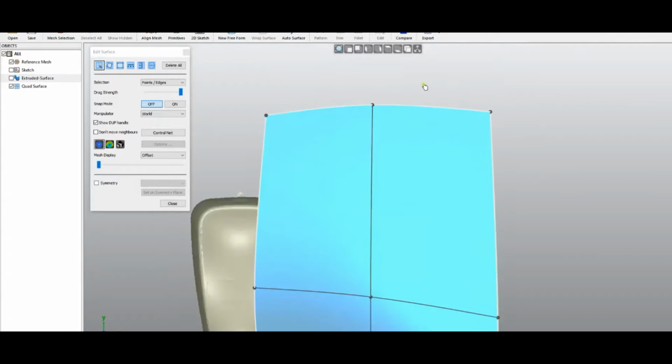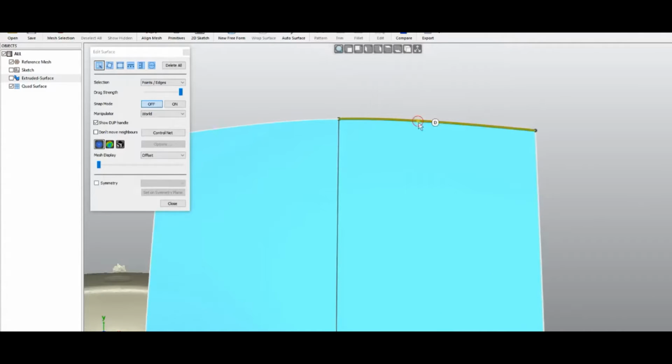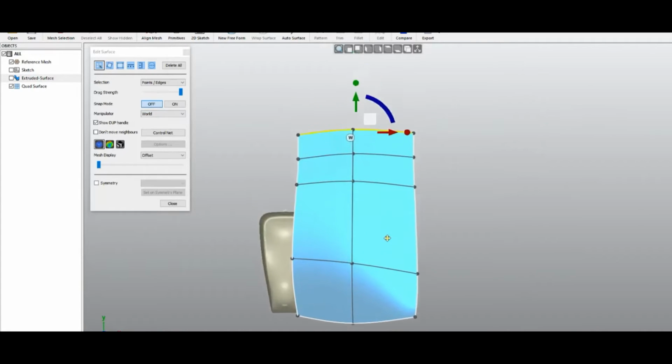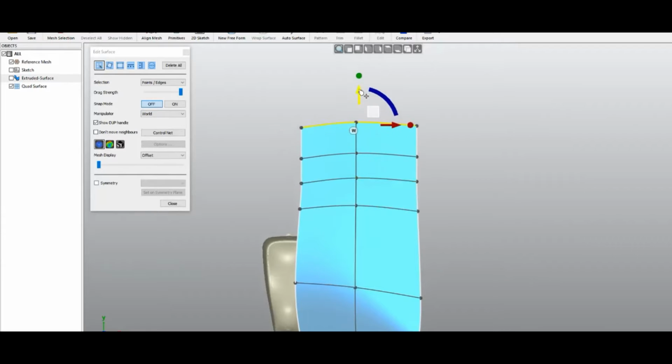Another way of duplicating an edge is, if you double click and select everything, you hold the Alt key, and instead of using the D sign, if you hold the Alt key while holding it and then you move, it will duplicate the edge. This is useful if you want to make really exact extruding of the points here.